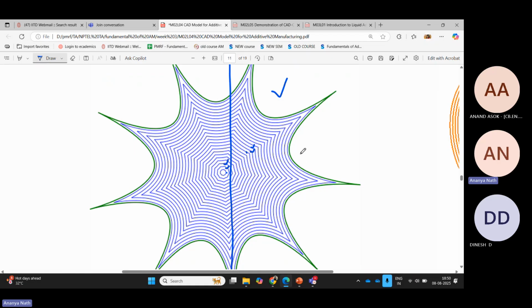So that means to print this simple geometry, the head or the system or the tool needs to have 23 times of on and 23 times of off. Each turning on and off will take some current, and each turning on and off will have some inertia as well.